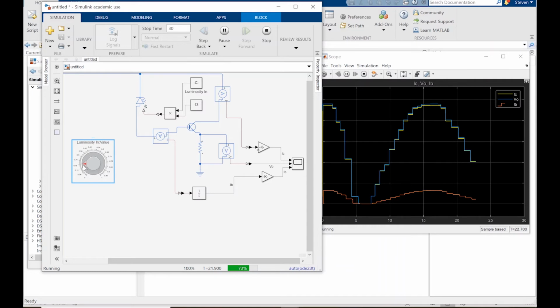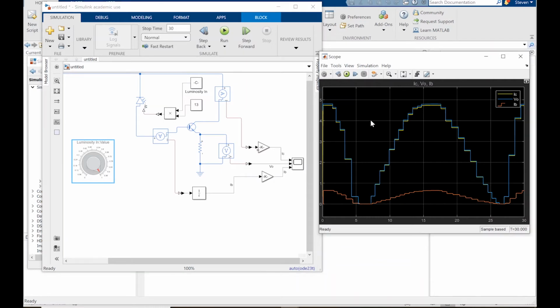But again, basically I want a positive correlation. I want the more light that shines on it, the more voltage that goes to the output. Now, in this circuit that we're going to build, there are many ways that we can invert that. If I wanted it to respond to less light, so the less light that shines on it, the higher the voltage goes, I would just use a common emitter, put the resistor up at the collector, and tie the emitter of the transistor to ground.